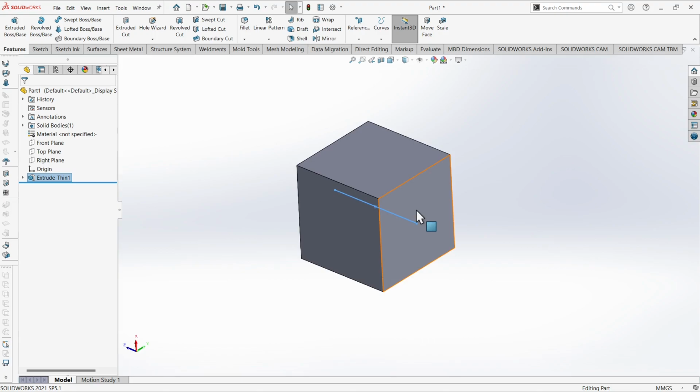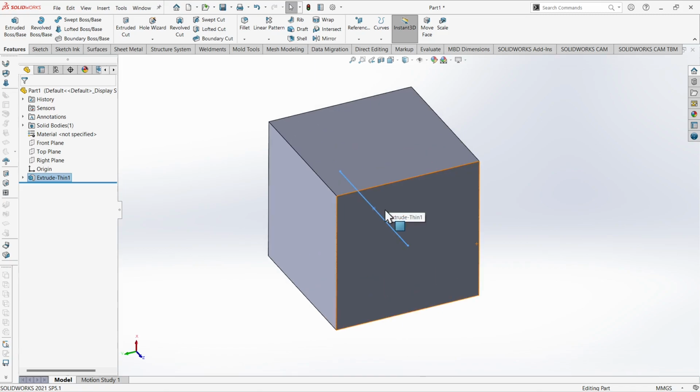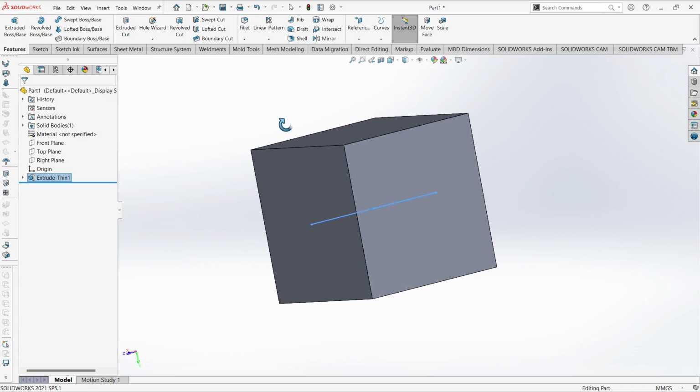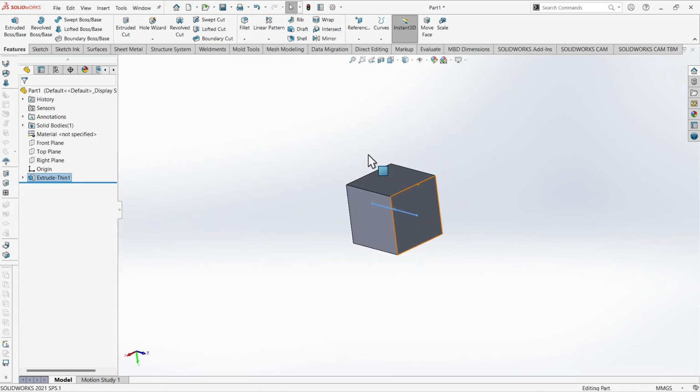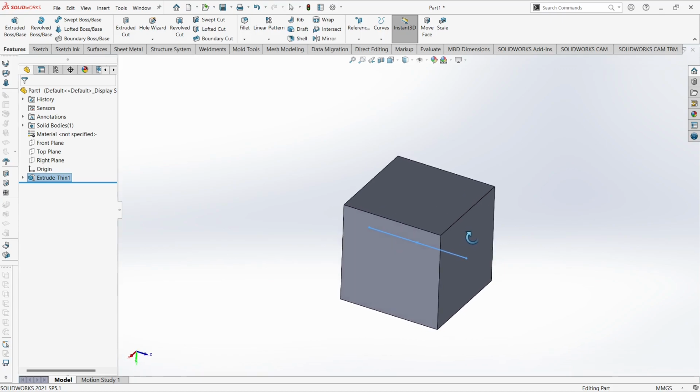So you see, with the use of thin feature, with just one line sketch we are able to make a cube. So this is actually a very beautiful command, because we need to make a comparatively smaller sketch. Smaller sketch means less chances of error, and we can easily edit it. So I personally prefer this over the traditional way, because it is very quick and efficient, of course.